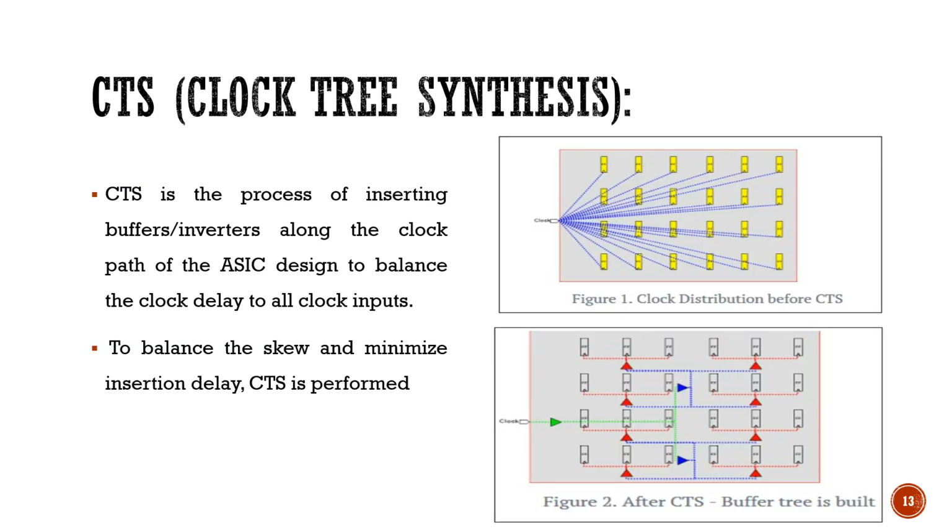What is this clock tree synthesis? Before going to the definition, let me explain the cases that are available in the figure. When you look into figure 1, this figure 1 comprises a number of flip-flops that are going to be controlled with the help of a single clock, which means it is an example of a synchronous network. So when you are using a common clock for all the flip-flops, we can't ensure that all the flip-flops will be turned on simultaneously.